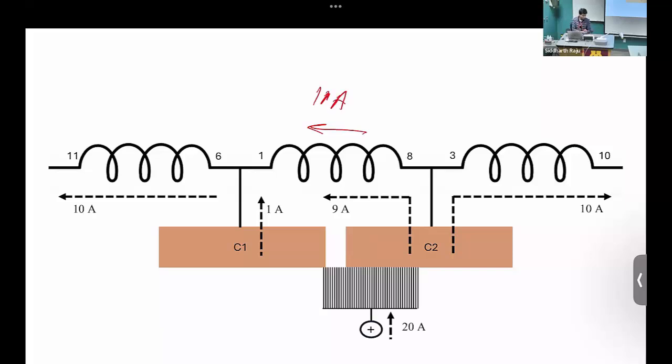Right? Yep, John. Sorry, just to clarify, so we're saying that current in the middle inductor can change because it's like a lower resistance path with the brush, right? Yep. So think of it like you have an inductive coil with some current through it, and you have some external resistance, and this resistance is increasing. It's not a perfect explanation, as I'll get to in a second, but as the resistance keeps increasing, the energy is being dropped in that resistance. So half L i square is going to drop in the coil. So all of that energy is dropping, then the current in the coil also starts to reduce. So that's what is happening here.